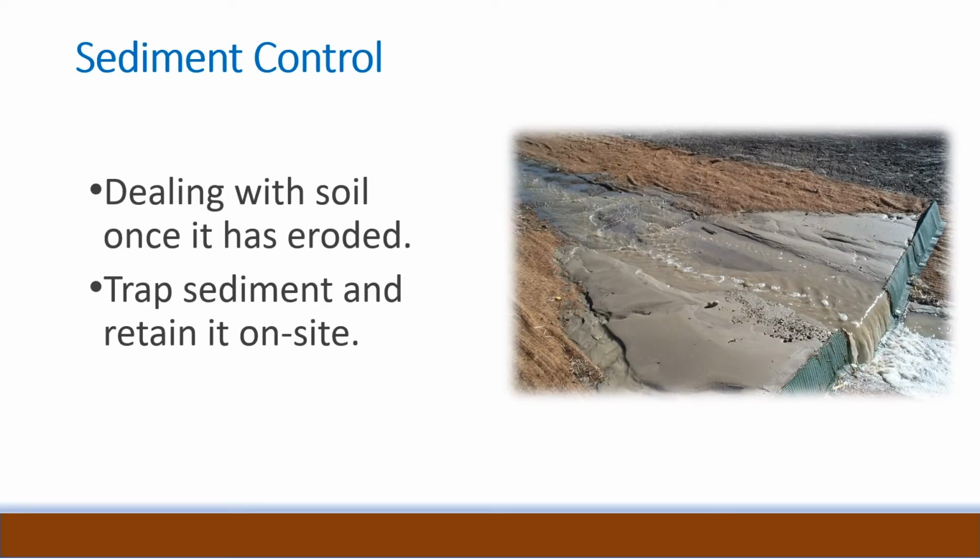Sediment control is dealing with soil once it has eroded. You are trying to trap sediment and keep it on site. Runoff is temporarily impounded behind the practice to allow soil particles to settle out, and water will infiltrate through the soil.